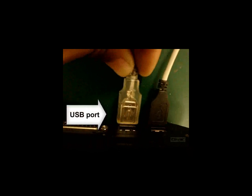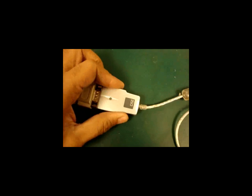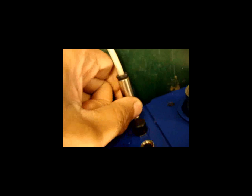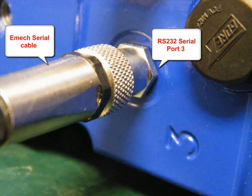Connect one side of the USB to serial adapter cable to your PC or laptop's USB port. Then connect the other side of the cable to the supplied serial cable. Then you screw the serial cable onto the port labeled 3 on the underside of the actuator.